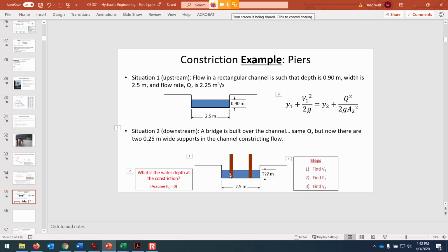Okay, so that's just another supporting example that goes along the lines of specific energy diagrams and how we find out what's the flow depth when there's something like a step down or a step up or a channel getting narrower or getting wider. We usually find that we solve the cubic equations and then we decide which route to select based on the flow conditions before that obstruction occurred. Are there any questions on this example before we conclude for today?